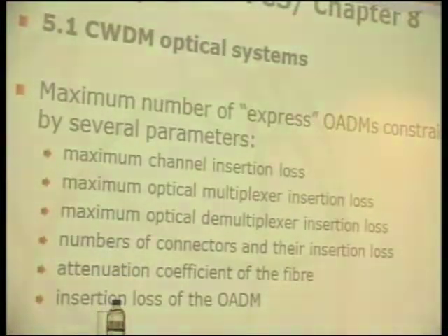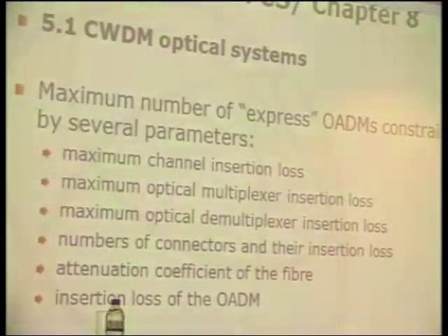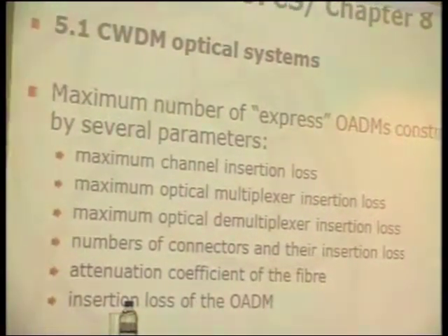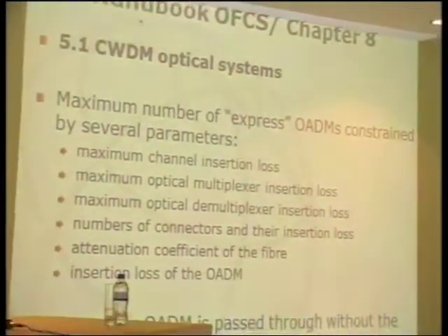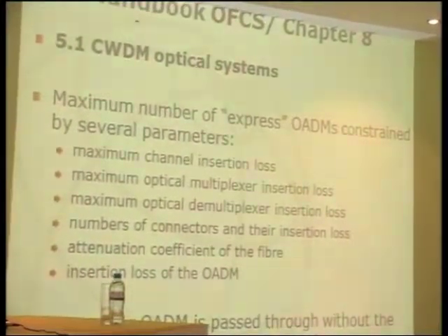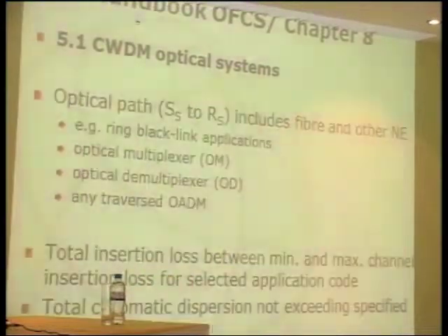And it will depend also on the number of connectors and on the number of splices along the line. The term express OADM simply means an OADM in which there is no add or dropping of wavelength. Of course, the OADM can be express for one wavelength, but not express for another one.